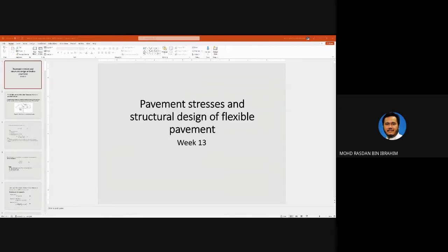Aggregate content, for example, if you change the type of aggregate, or you add in palm oil kernel, something like that, that will increase the absorption of bitumen, and thus increase the amount of optimum binder content that is needed.